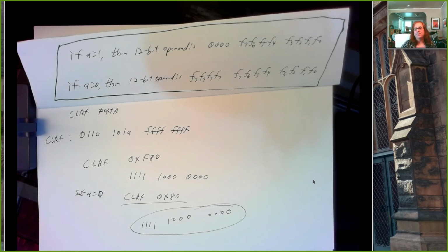So this is goofy. This is what you get with a RISC processor, where adding 4 more bits to your instruction cranks the price of the hardware up to a point where you can't compete anymore. So you put the burden on the programmer to work with something like an access bit to keep the price of the hardware down, keep the size small, and so on. This kind of thing happens all the time with RISC processors. It's a quirky mechanism, but it's a way to save hardware, basically.